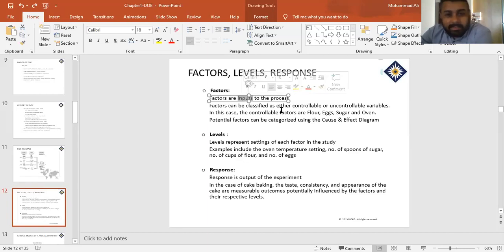So for that, we need to do an experiment to find exactly at what pressure the first bubble comes out. What we do in that case is raise the pressure and then depressurize the oil, and we observe it from the camera or from the window until the first bubble comes out. So that was our input parameter, which is the pressure.